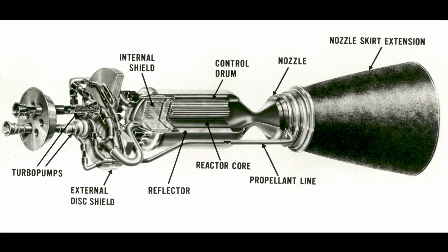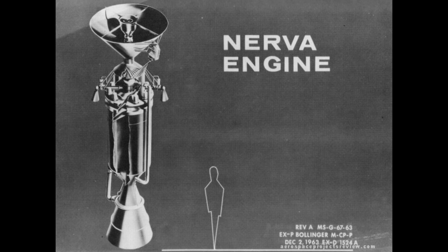There is just a limited temperature that a solid core can have, and a limited temperature that a reliable structure can sustain, and therefore the specific impulse of these is way below the theoretically energetically possible for a nuclear rocket engine, but therefore they are reliable and realistic to build.